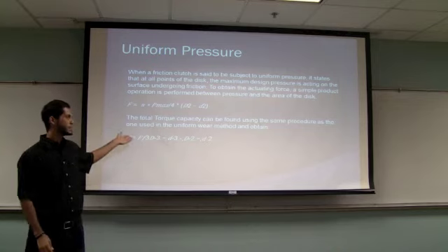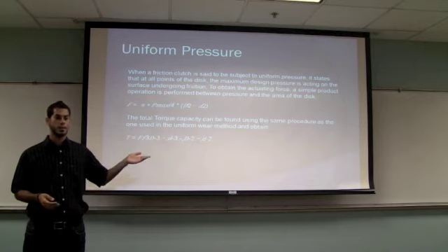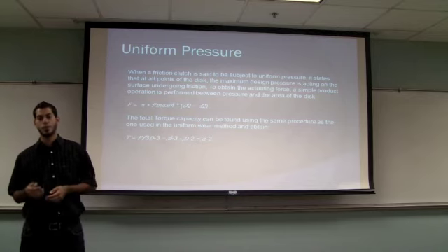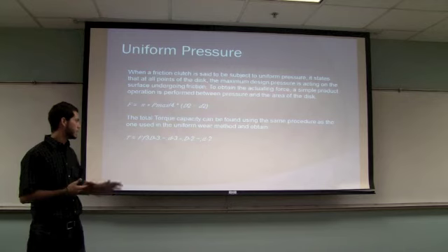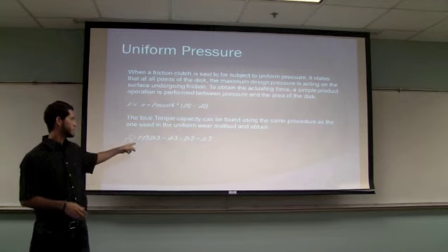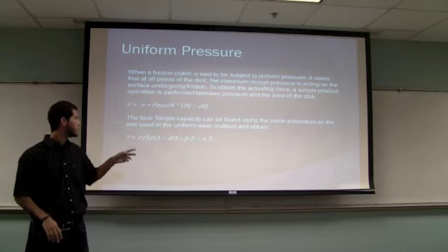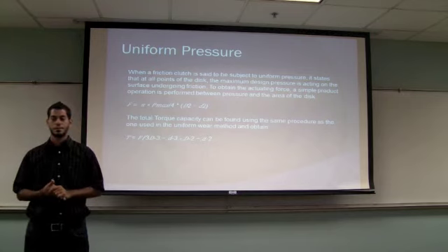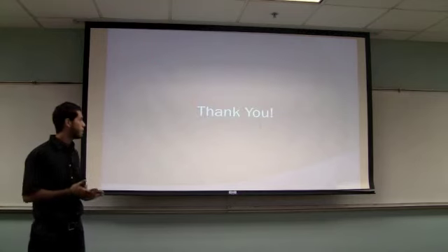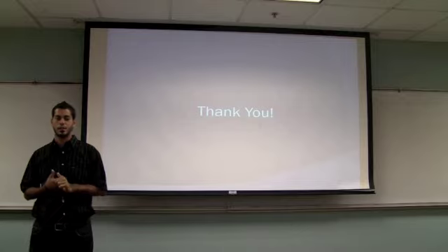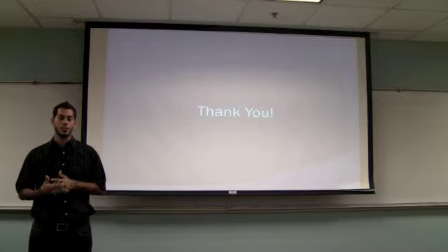The total torque capacity can be found as was done before in the uniform wear equations. It just has a few variations. These terms here should be all cubed and squared. And that's basically how the clutch design mechanism would work for a friction clutch.